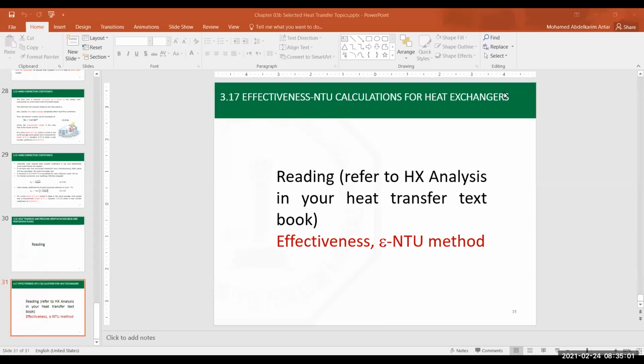In many cases, the solar collectors are connected to heat exchangers, especially if you are using some sort of ethylene glycol as the heat transfer fluid that would pass through the heat exchanger, so that you would avoid, for example, the occurrence of corrosion. If you used raw water, you might use additives to avoid corrosion, so that you would not like the water passing through the solar collector to come into your system.